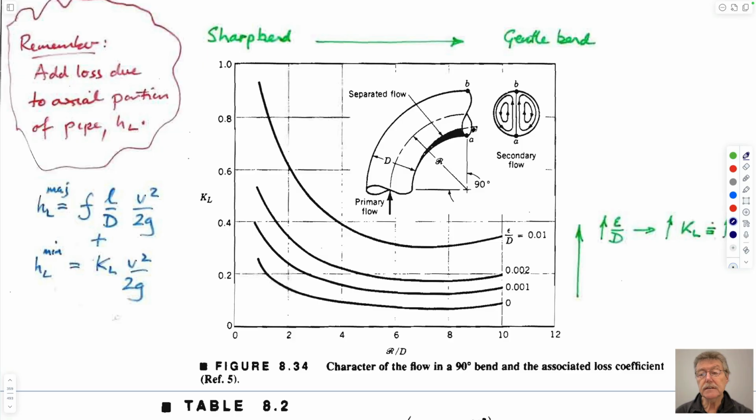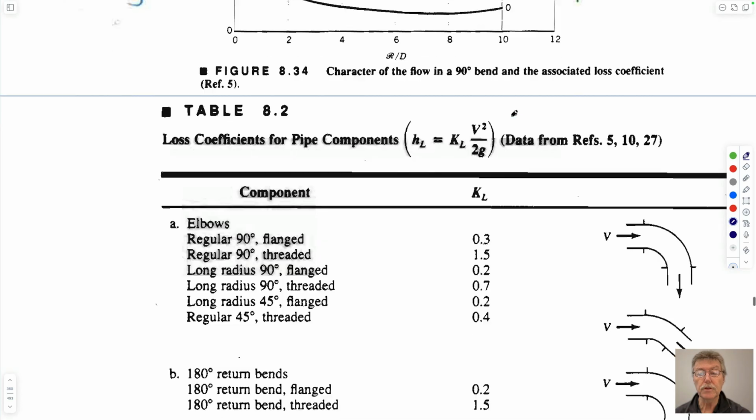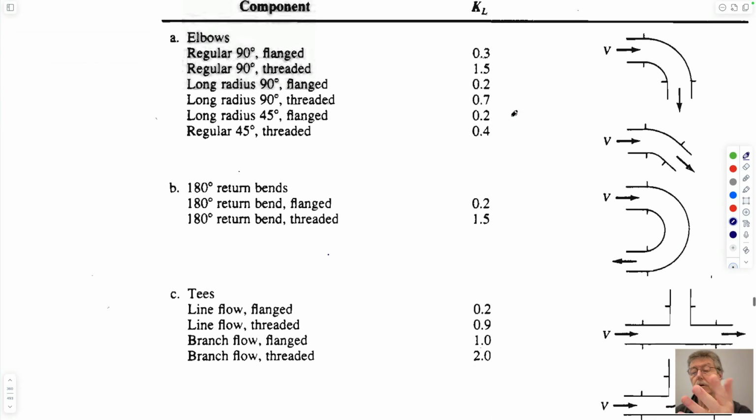When you go around bends, if you go around a horizontal bend, you can imagine a separation in the middle of that bend where you get circulation on either side of that mid-side line, which is really what's being shown here, as a secondary flow, and you could work that out. And this is perhaps the only thing that we'll need to really understand here. And that is, one, that you can calculate what this loss coefficient is. So we'd like to calculate it as the sum of the loss coefficients times average velocity. And it should be the average velocity in the pipe that precedes it or follows it. So this would be the velocity in the pipe going into it.